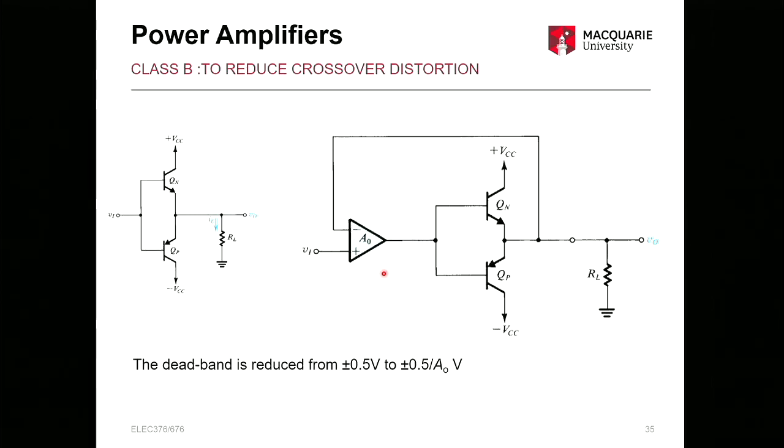Of course, that complicates your circuit. It's also limiting your frequency response a little bit, because the slew rate of the op-amp is likely to be slower than the response of your transistors, okay? So if you're in high frequency applications, the slew rate of the op-amp might become an issue. An alternative is to go to the Class AB, which we'll be discussing more next week. I'll show it briefly here.